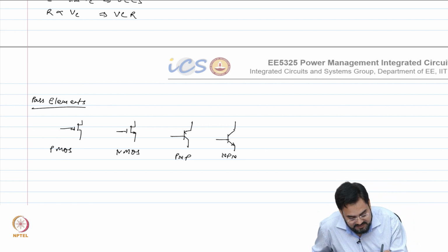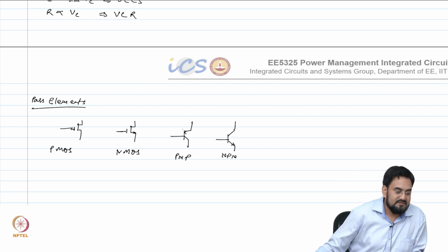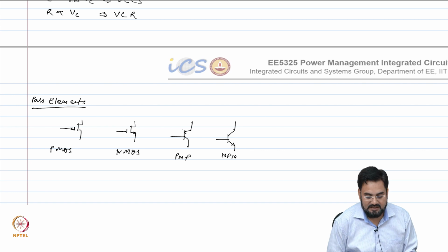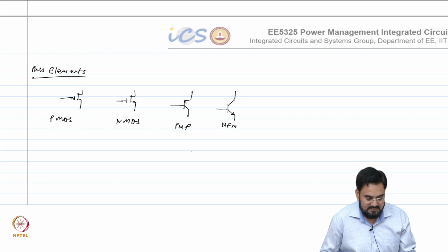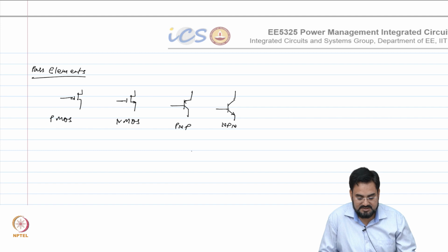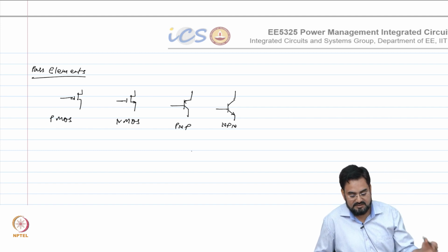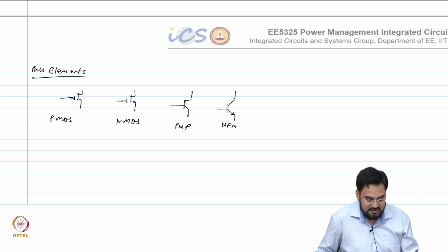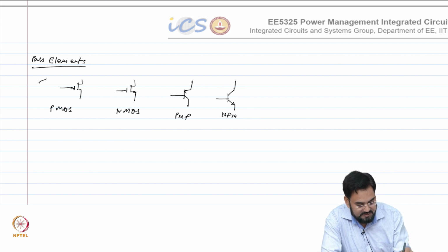and since we mostly use CMOS technologies where we do not get freedom of having active bipolar devices, we get only these parasitic bipolars, which we looked into in a band gap reference, where your substrate is grounded, which forms the collector, and you just tie the base with the collector. So, that is parasitic. So, that is why we do not have a freedom to use bipolar. So, we mostly use these two.